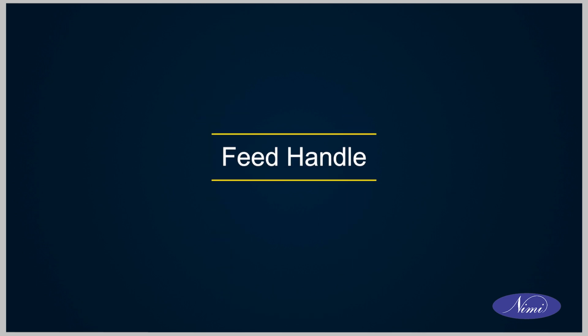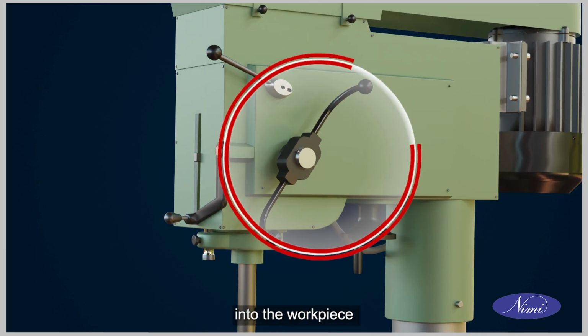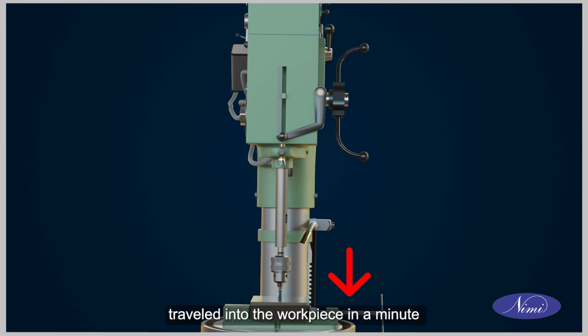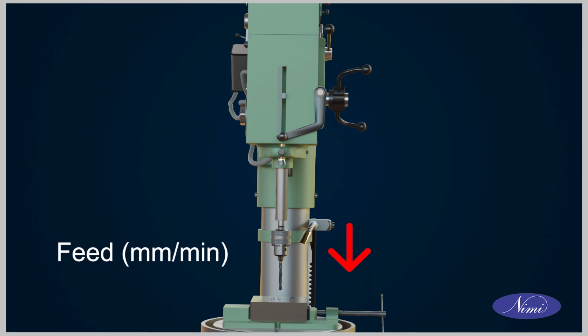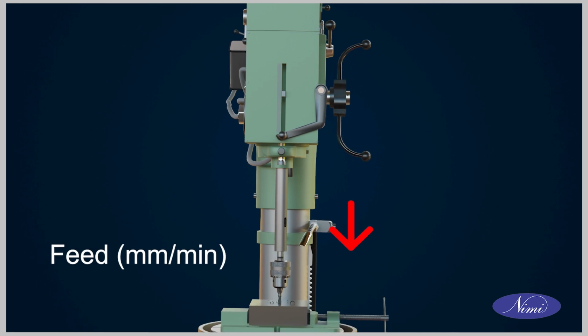Feed handle. Feed handle is used to feed the tool into the workpiece. Feed is the distance of the drill traveled into the workpiece in a minute. It is expressed in millimeters per minute.